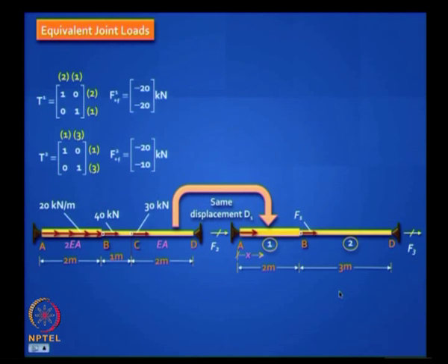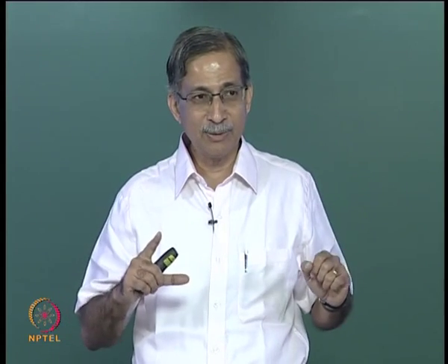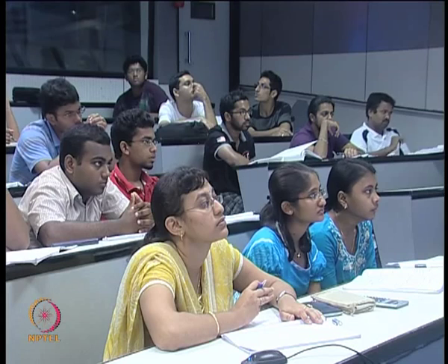So how do you do that? Well, you do it first noting down what you have already done. You have got the 2 transformation matrices, you have got the fixed end force vectors. What is the transformation you do to get the fixed end forces? You are now moving from local to global. So what is the transformation you need to do? TI transpose, that is all you do.